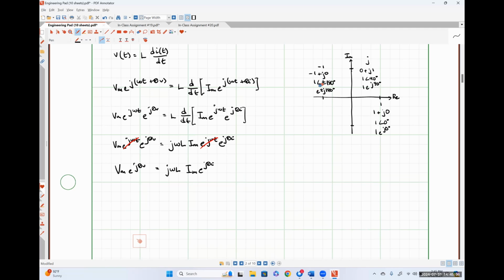That 1 doesn't look like a 1. And then lastly, if we went 1 unit in the negative imaginary direction, we normally call that negative j, which would be 0 minus j1 in rectangular form, 1 angle negative 90 degrees in polar form, and 1e to the negative j 90 degrees in exponential form.